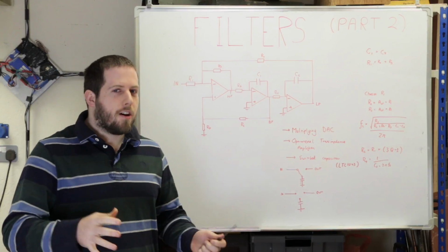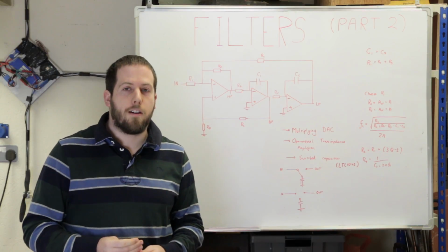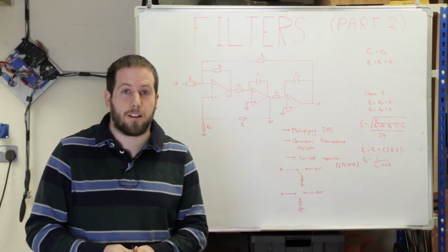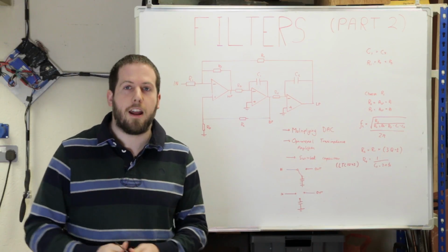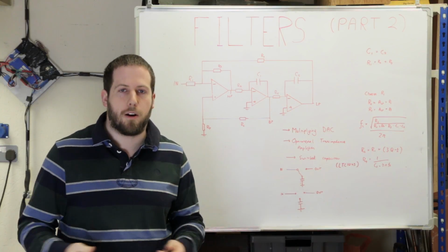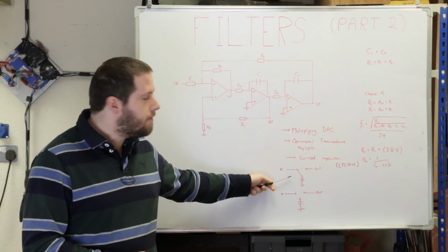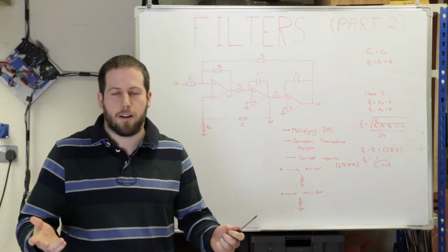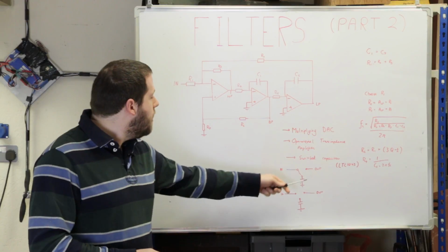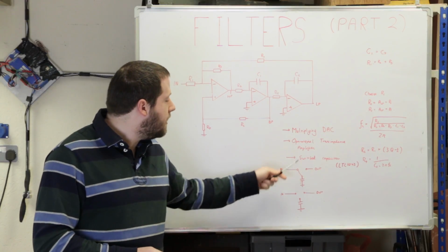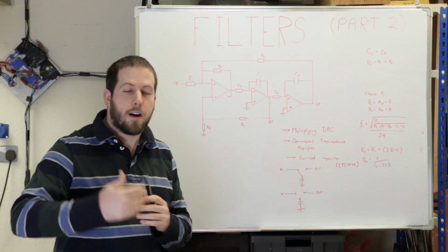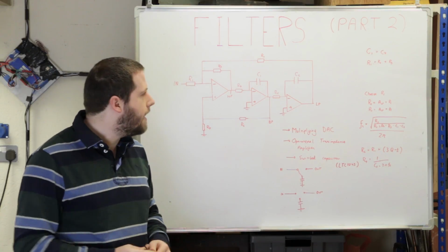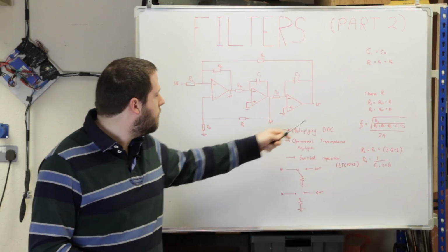Generally, driving that is a little bit more complicated than driving something like a switch resistor. A switch resistor takes a pulse width modulation signal in, which of course is really readily available on basically every single microcontroller out there. This, you want a variable frequency signal. It's a little bit more complicated to generate, but not rocket science. And again, you want your switching frequency here to be nice and fast, much faster than your filter cutoff frequency. And that's implying using the low pass output.